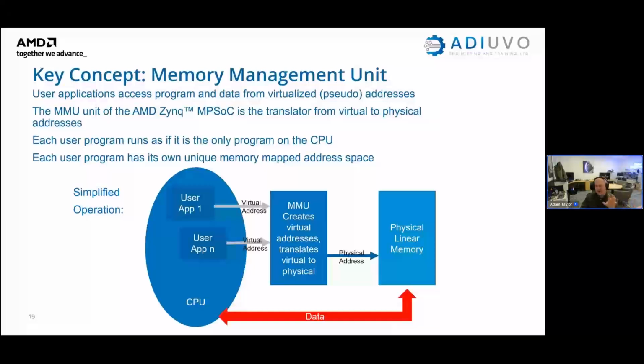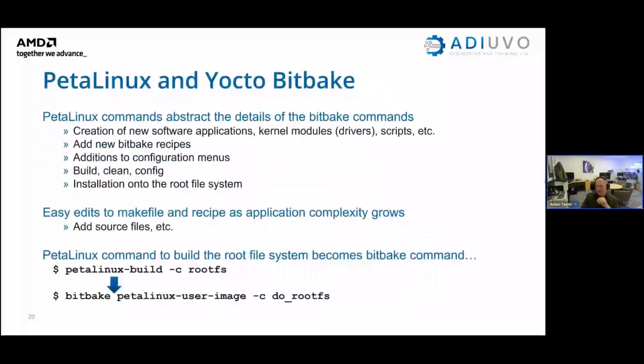If we want to, though, we can punch through this. There are tools like devmem, which will allow us to just jump through and punch through that. But we have to be very, very careful with this. So let's be careful with that and try to use sensible things such as UIO to do that interaction with the peripherals, because that's what it's intended to do.